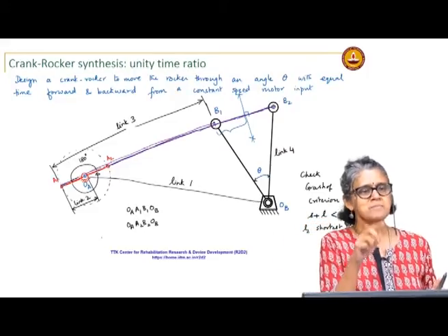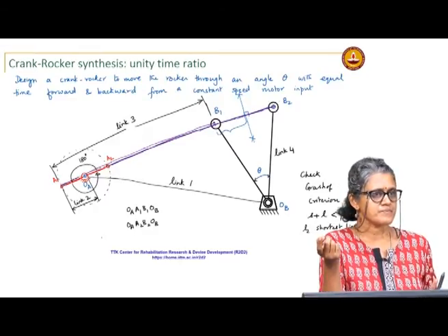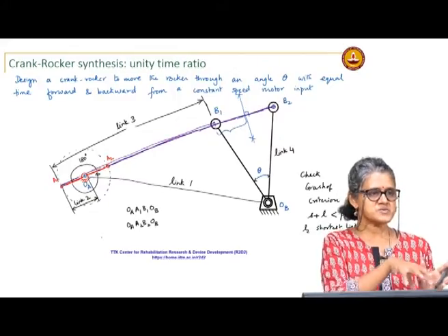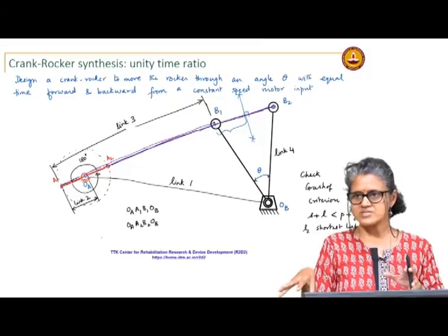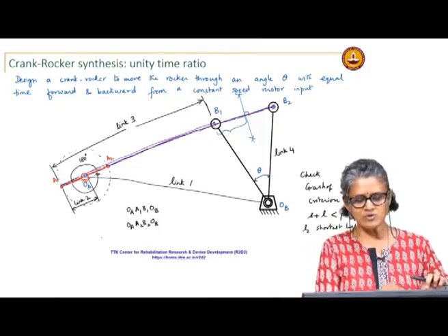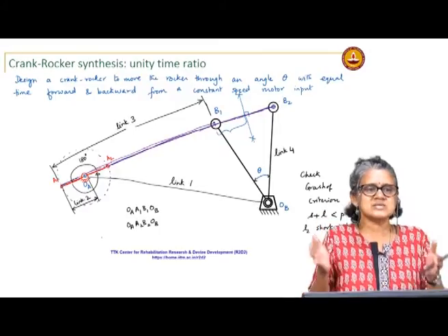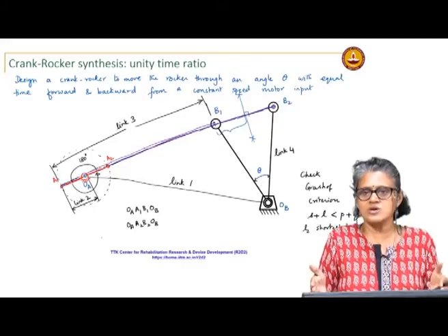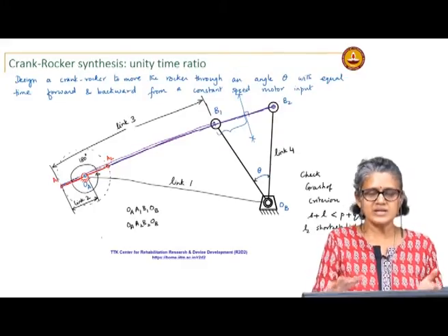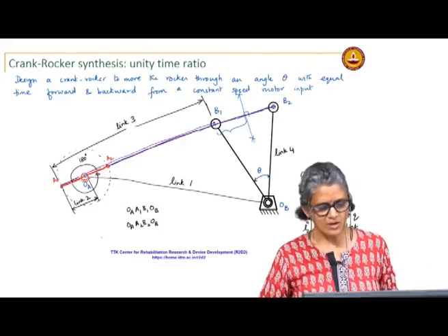That is something that you will see with all function generation problems, because the angular relationships between the input and output link are what you are concerned with, and that does not change when you reorient the linkage. So, I could design this and then finally orient my linkage such that my OA OB is horizontal, which is fine. It will change the orientation of the other things.